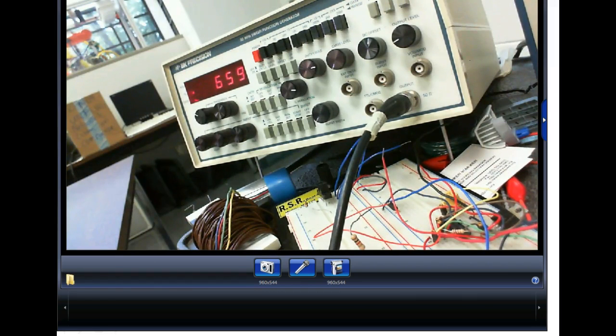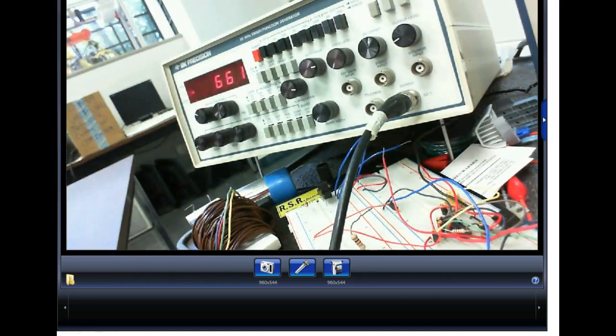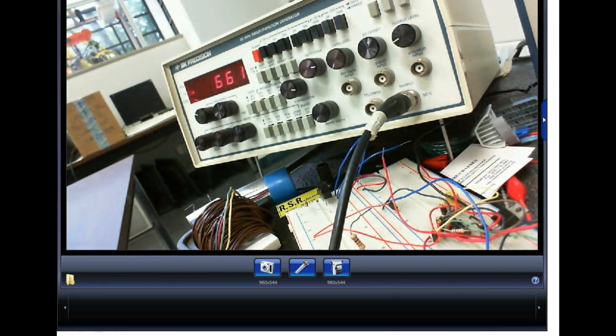And they're really neat for troubleshooting, especially stereo equipment and stuff like that. Because if you've ever seen, audio is all over the place. So it would be impossible for me to look at the frequency response of an amplifier while it's actually operating. What we can do with a function generator is inject a signal into it, and then I know what I'm putting in, and I know what to expect out, right? You understand? Because I'm putting the signal in. So if you're going to troubleshoot stereo equipment or stuff like that, well, no, the actual stereo.